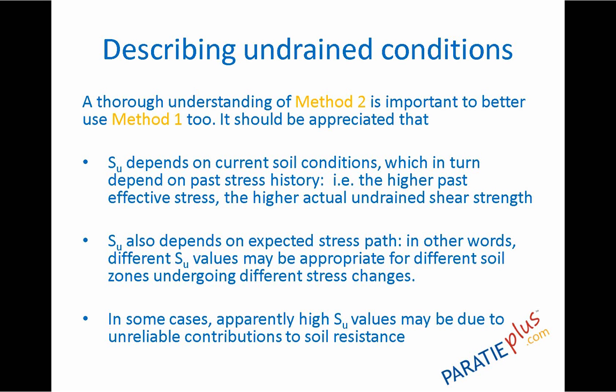So it is important also to remember that the higher the past effective load going over the soil, the higher will be the actual undrained shear strength. And also the undrained shear strength is not just one value for a soil. In other words, there may be different undrained shear strengths depending on the expected stress path which the different zones of the soil will follow during excavations.